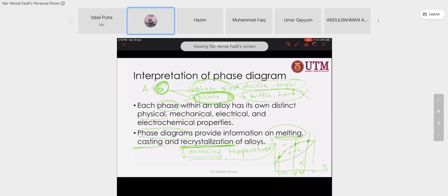And 0.4 melting temperature in Kelvin. So you need to convert it into Kelvin, degree Kelvin, and take 0.4 out of it. So it is 0.4 melting temperature in Kelvin.